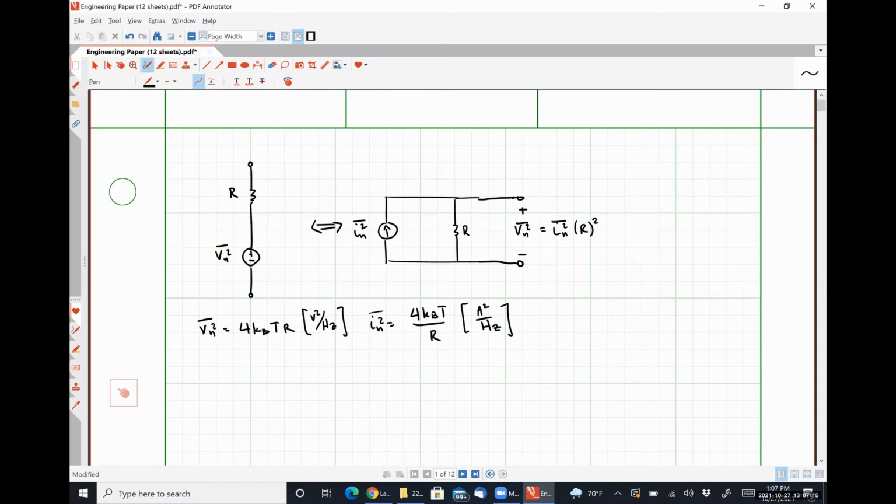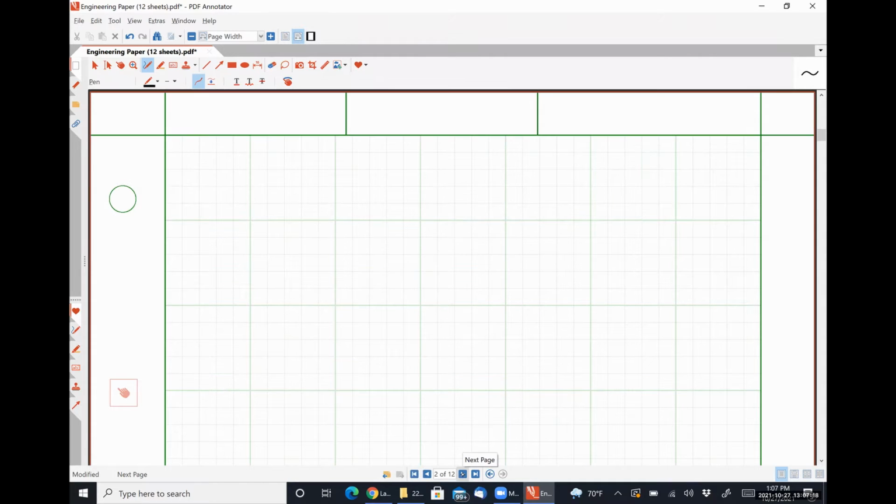All right. So with that taken care of, let's talk about thermal noise in MOSFETs. So this is a continuation of our discussion of thermal noise. All right. So as I believe I mentioned at the end of our last class meeting, MOSFET transistors also exhibit thermal noise, with the most significant source being what's called channel noise, which is caused by electron fluctuations during the inversion process, okay?